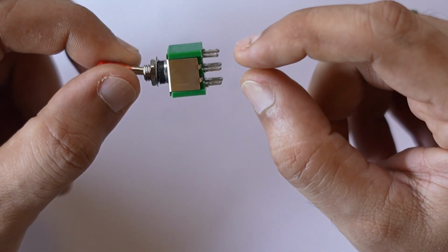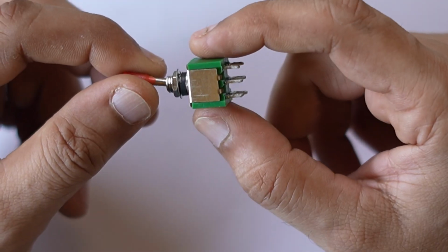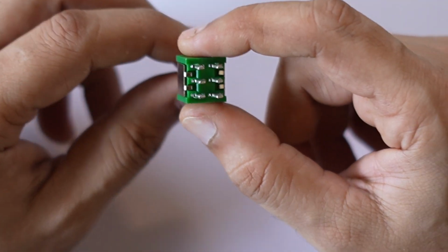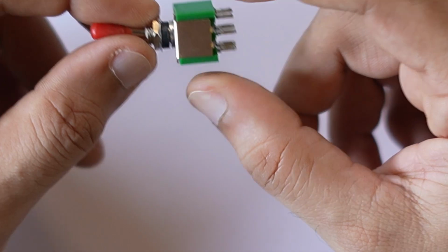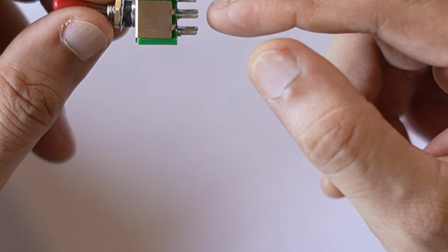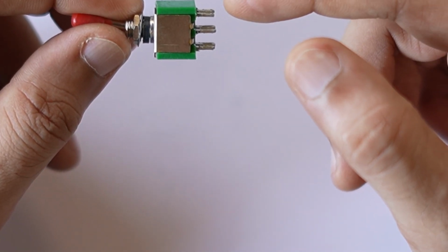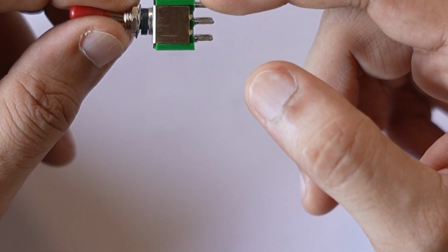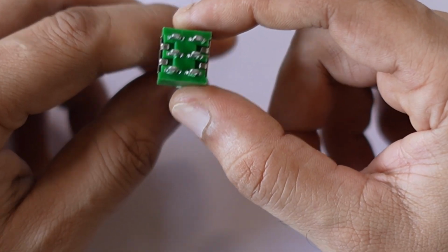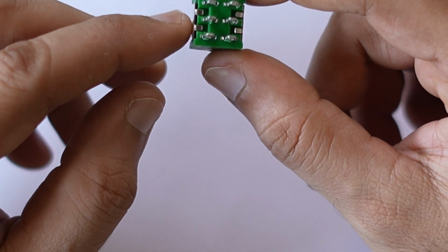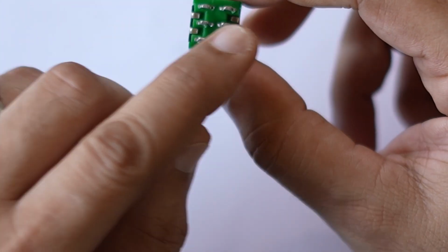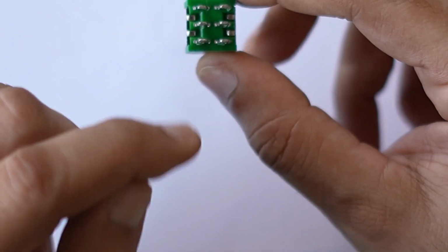And then if you flip it over, you have the same effect on the other side. So technically 2 switches that are being operated at the same time simultaneously. And these have what are known as changeover contacts. So your center is common and you have one contact at the top, the other contact at the bottom. And then you can also have these in what are known as double throw switches because they have 2 poles or 2 different switches in one.